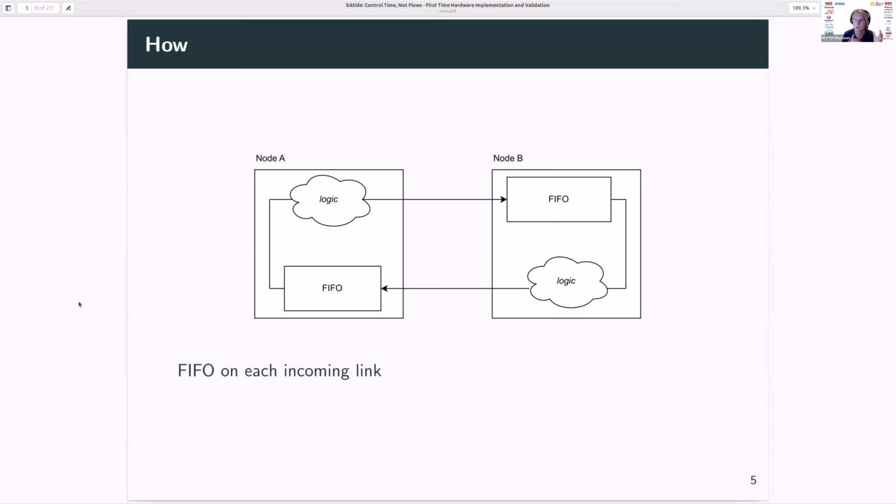So one node might boot a little bit later than the other, and so you get a huge difference in the clock cycle counters. But crucially, this number will stay exactly the same during operation. Now, note what we can do with this property. We can statically schedule computations and communication.